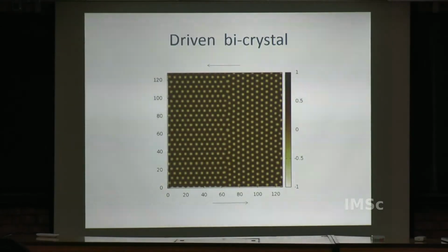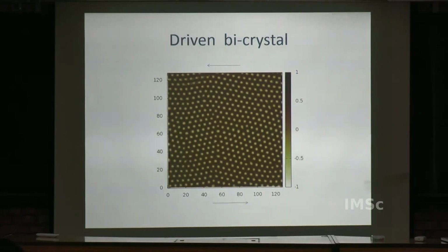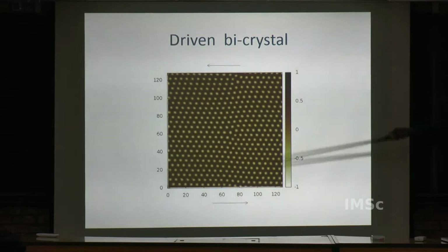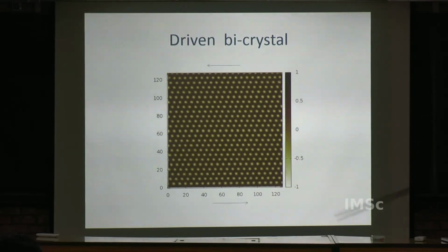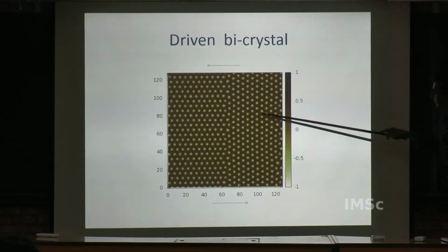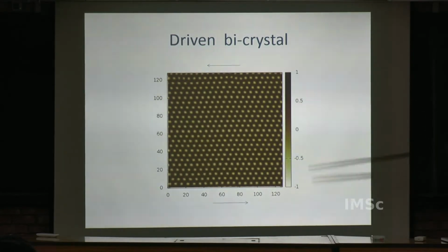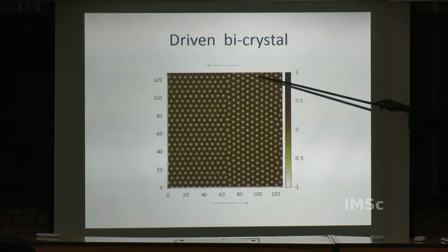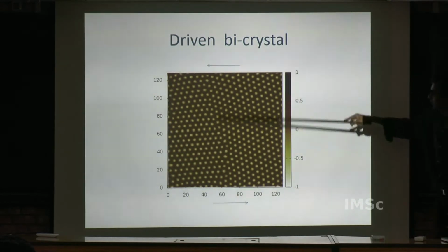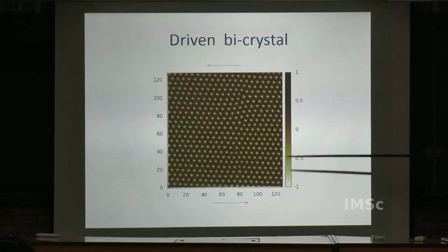Okay, so here is a simulation which I will repeat. This is a simulation of a bicrystal. You have periodic boundary conditions with a phase field model. So now there is a bicrystal. You see that dislocations, that is atoms, are moving, and in the final state these two layers are moving, and the in-between thing has become a single crystal.